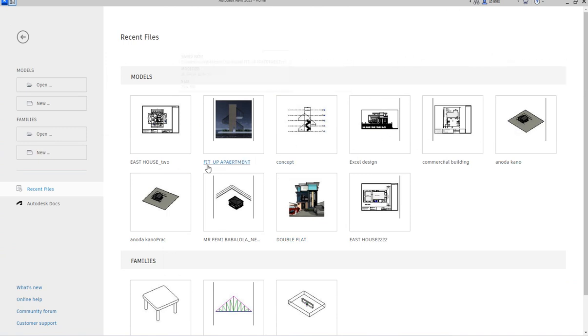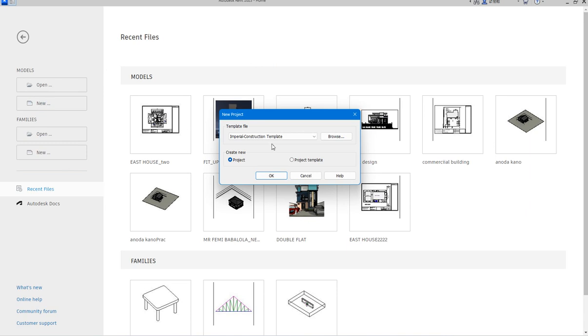So here is the project as it's been said. These are the previous ones that I've done before. So I'm starting this afresh now so that we move on from here to the next beautiful project. So now, if you have this one, you open your Revit. This is what you are going to be seeing. You start by clicking on New Project. So here is the new project template, which is what will appear.